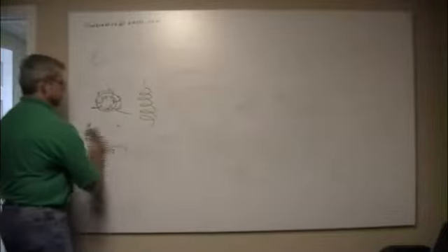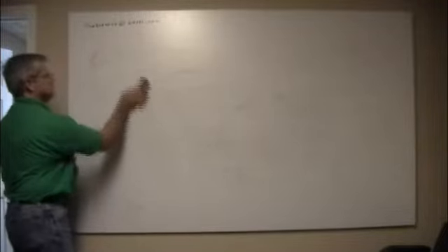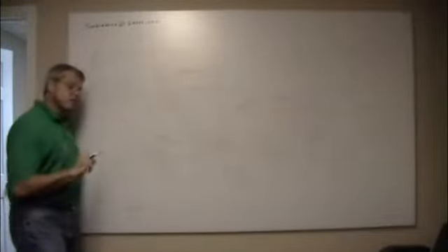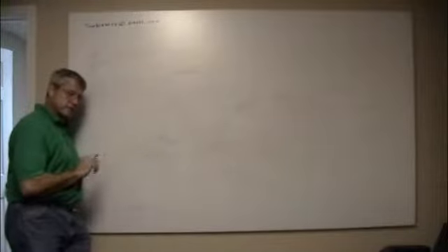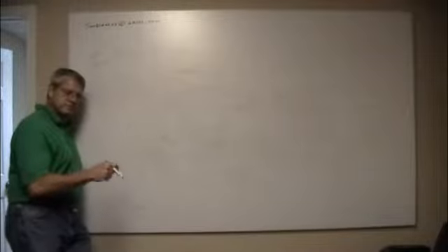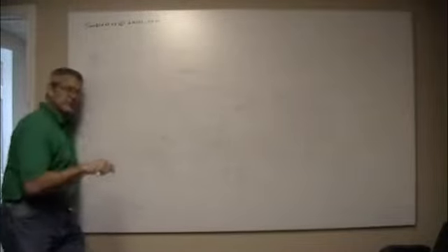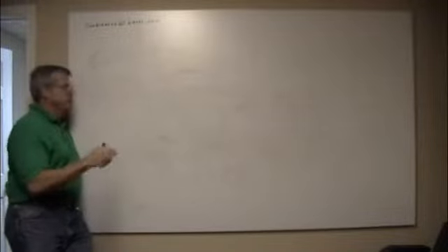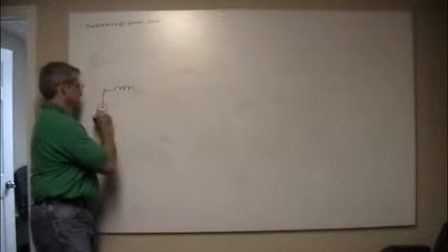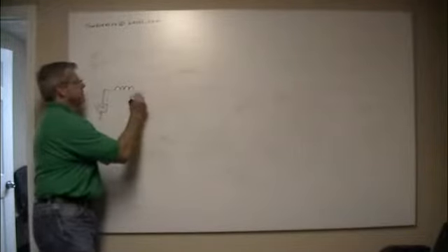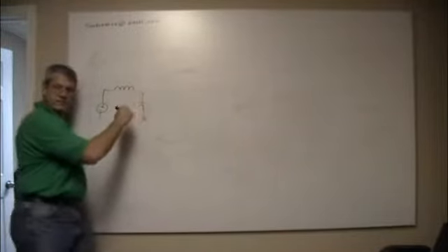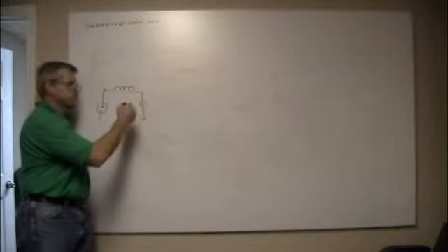The other thing we can do is make oscillators with them and capacitors. The most common use, I think, well, there's two. If I've got a power supply and a circuit that's doing a lot of switching, it grabs energy and gives it up, and it's not a level load, I can put an inductor in line with my power supply, and again, a capacitor here. Remember that feeds energy as we need it.